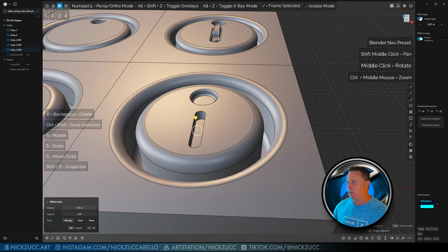And then the next thing I'm going to do is I'm going to tap F. I'm going to find bridge, and I'm going to bridge curve. Now, I have tried this out already, and it does work, but it depends on what the direction is that you're going for this curve. So if I go from this part to here, it doesn't exactly give me what I'm looking for. I'm going to hit undo for that. And I'm going to do Shift R to repeat my last command of what I just did.